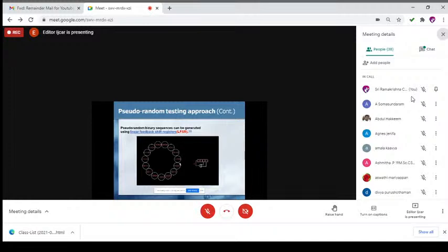Now we can see how it works. For example, if we have a 4-bit generator, it will be based on the linear feedback shift register structure that we can see here. This is the basic hardware structure: the last 2 bits are run through a 2-input XOR gate. And you can see the loop will be repeated after 15 periods.